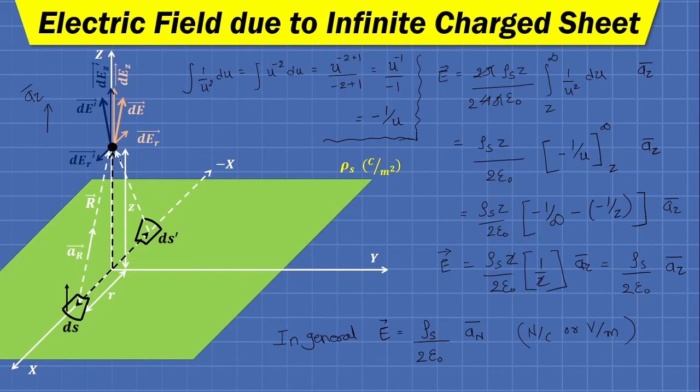If our point P, say it is somewhere under the xy plane, say over here we have P prime, fine. So at this point the direction of intensity will be downward normal, so this direction will be negative az bar, fine, because due to such an infinite sheet the field will be normal to it anywhere in the space.